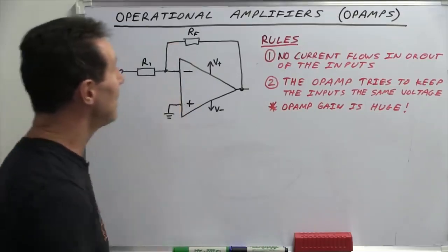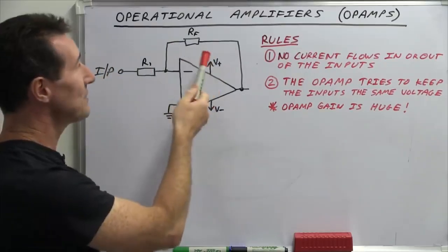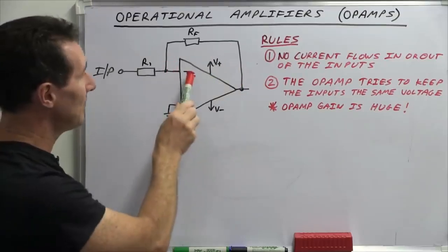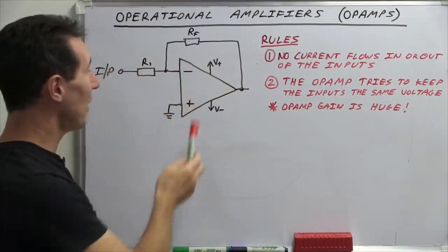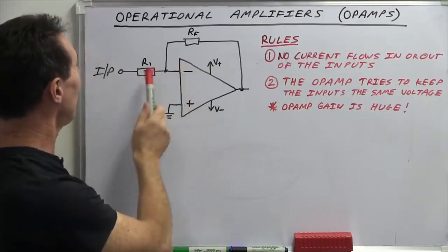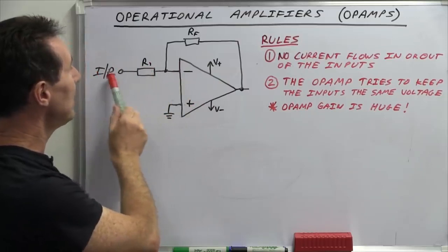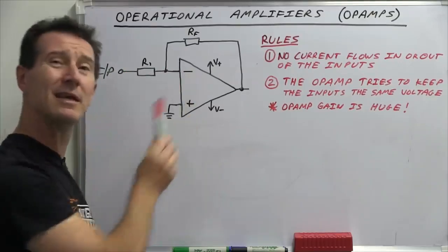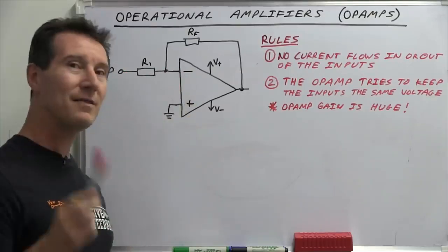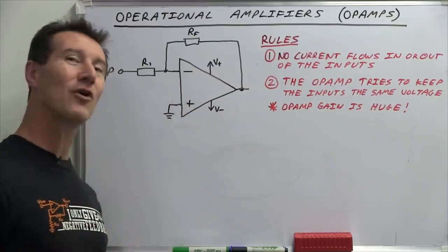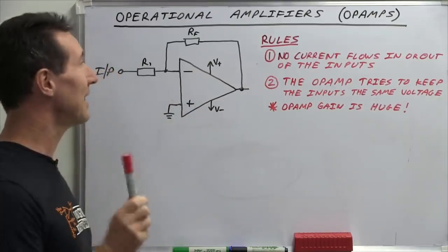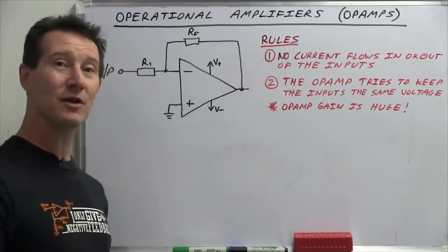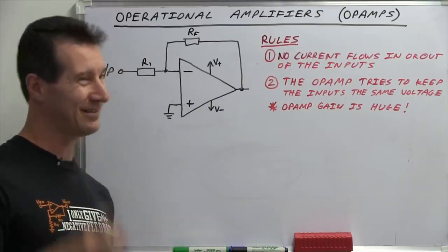Now, our inverting amplifier, that this one is, we have the same as before. We have our feedback resistor, we have our negative feedback going to, in this case, our inverting amplifier pin instead of our non-inverting one. So now we are feeding our input through the resistor here. So it's a different configuration. Our signal is not going directly into the non-inverting pin. And this brings up our next really important concept with op amps that you really need to understand. And here's where rule number 1 really comes into play in trying to analyze this thing. It's called virtual ground. Stick with me.